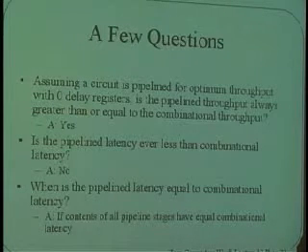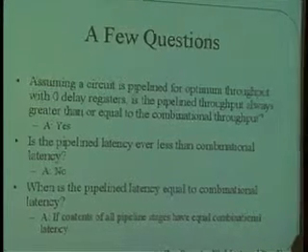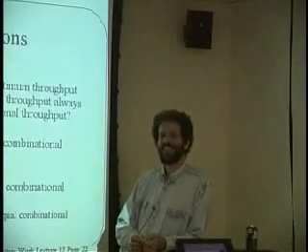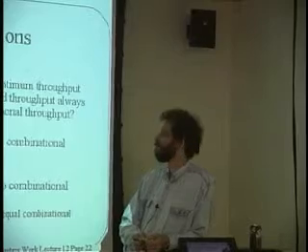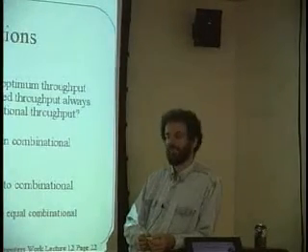Is the pipeline latency ever less than the combinational latency? No. Why is that? That's actually what you answered, which is that we're not routing around any pieces of combinational logic that we need to do. Good. Absolutely right.